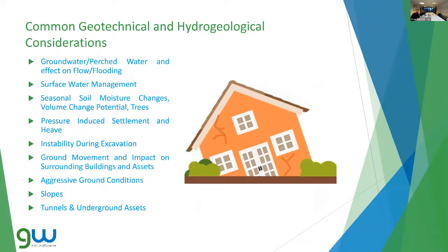I will talk a little bit about the common geotechnical and hydrogeological considerations around basements. We have groundwater and perched water and the effect on flow or flooding. We have considerations for surface water management, seasonal soil moisture changes, volume change potential, trees. It's the usual things you have in construction.